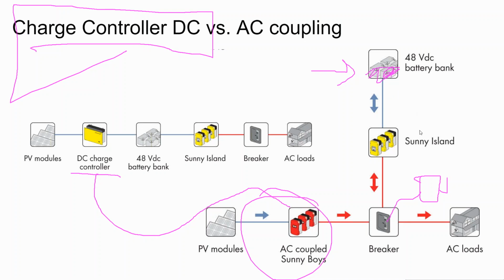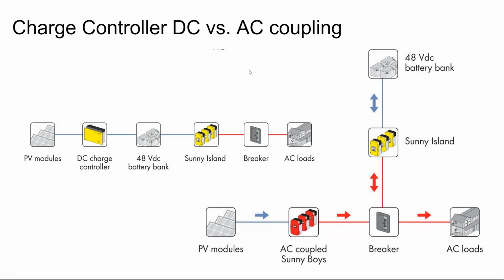And there's nothing wrong with AC coupling. In fact, it's the preferred method for commercial systems and utility systems for two reasons. One, it's grid tied, so most of your solar production is just going to dump directly into the load or the grid. And two, the high-end commercial and battery inverters come with their own dedicated inverter, much like the Tesla Powerwall. And so just clicking it onto the existing AC service panel will usually result in the easiest install.